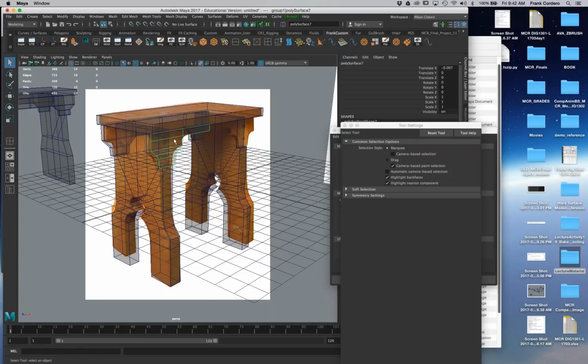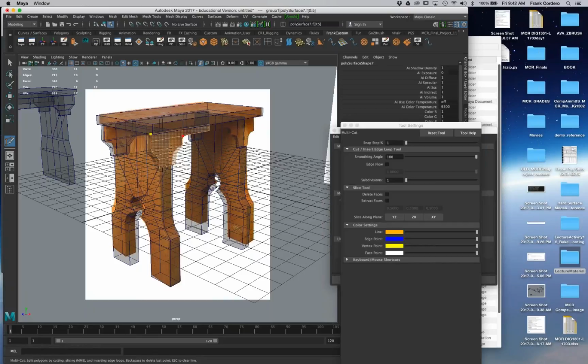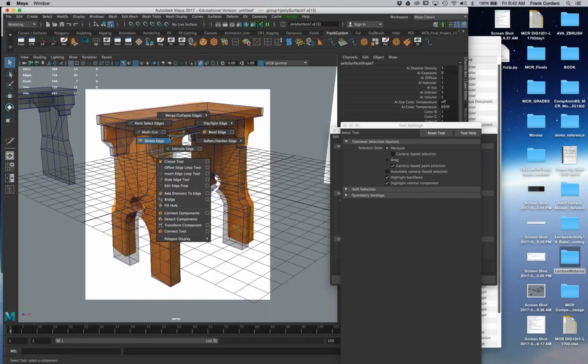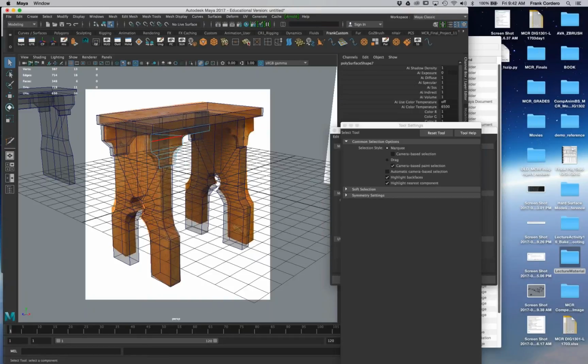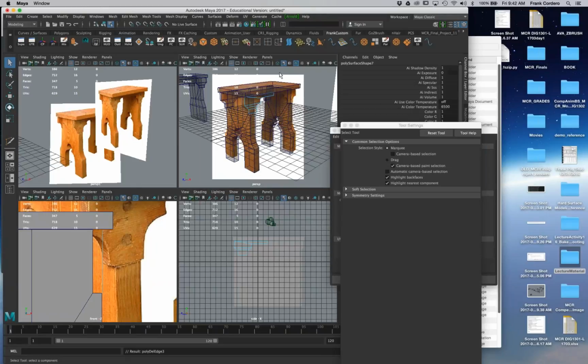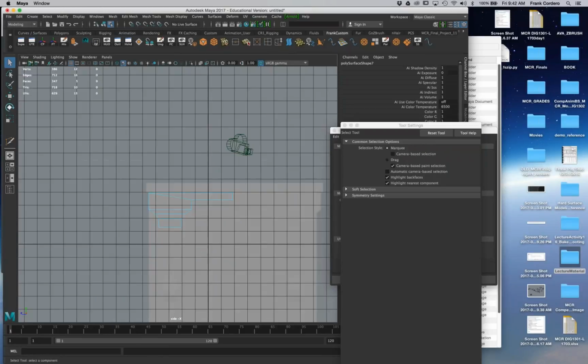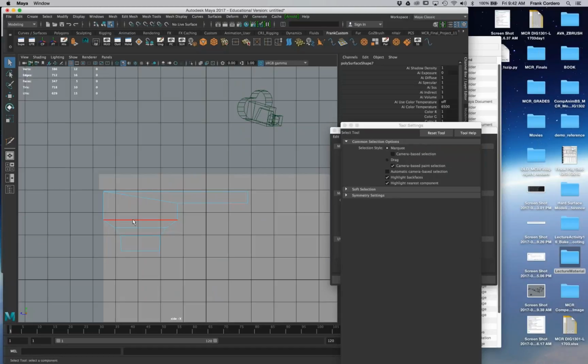You're saying, I don't get what you're talking about. Well, I'm going to go and use my multi-cut. I'm going to go from this corner to here. All right. And now I'm going to go and grab this edge, delete it, grab this edge, delete edge. So I changed the flow of the edge flow. So instead of it being up, down, I changed it so that it swept this way. Boom, boom, boom. Before it was a crisscross.